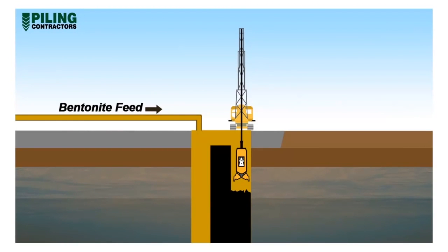Walls are constructed to tight vertical tolerance. Excavation of the diaphragm wall is carried out in panels. A typical panel is excavated in 3 bites: a left bite, a right bite, and lastly, removal of the middle bite. Depending on the grab type being used, 2 to 2.8 meters wide is typical. At the same time, the soil is removed from the panel.